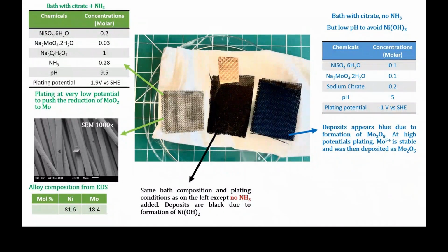And then, okay, well, let's just leave the ammonia out, because we realize that the presence of ammonia makes our silver-silver chloride reference electrode quite unhappy, which is why we went back to older papers, which all use calomel. So now we're sort of umming and ahhing about what to do, but not including ammonia clearly makes a not nice deposit, and trying to avoid citrate doesn't give a very good deposit. So we're still doing a lot of work on trying to identify the best plating bath and understanding the best conditions, but I've basically explained how we're doing that.